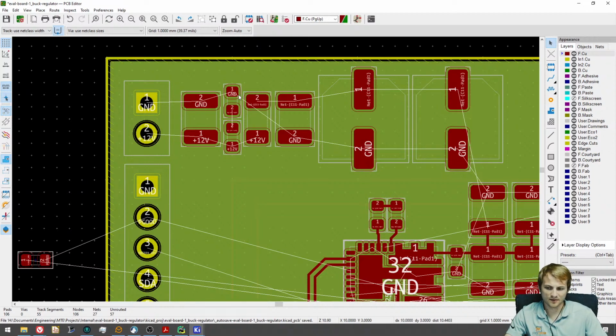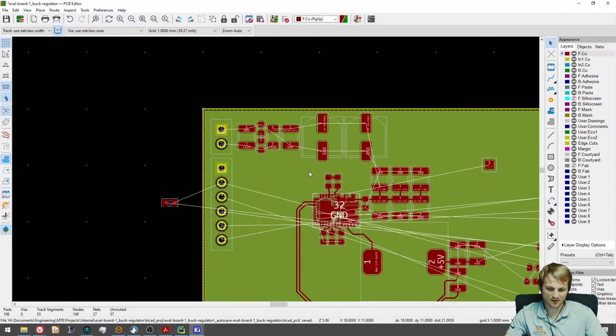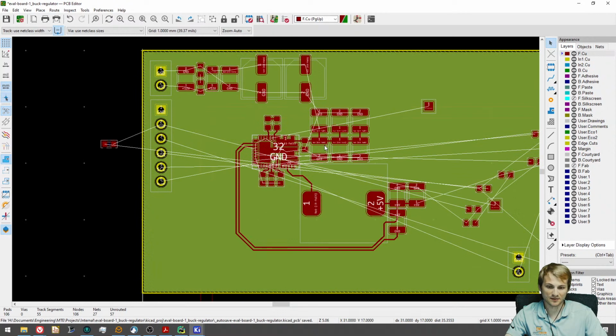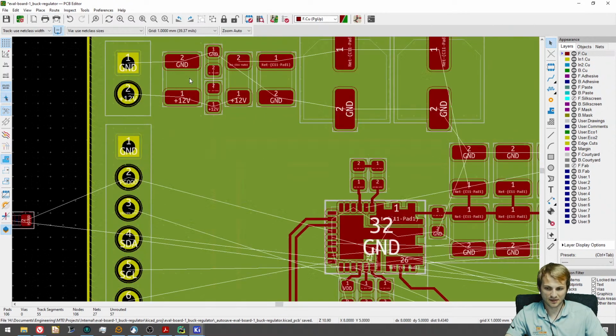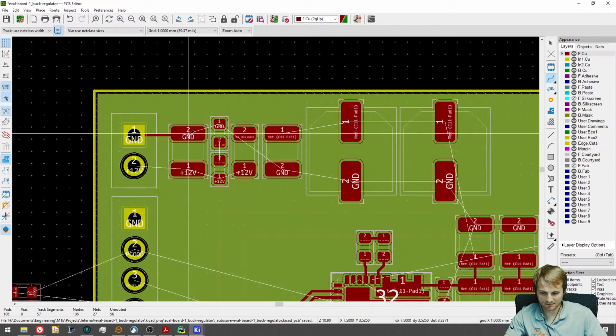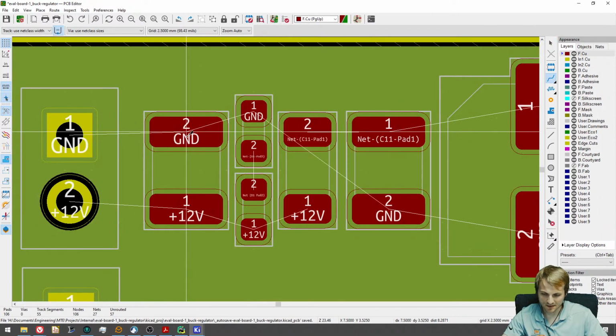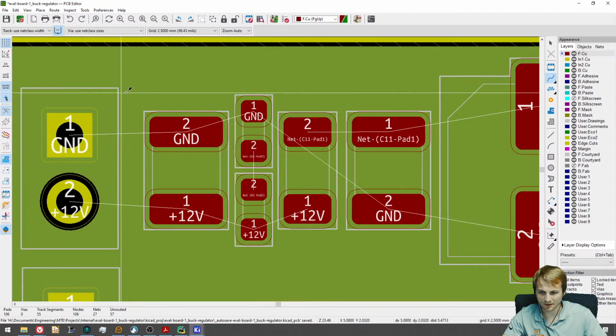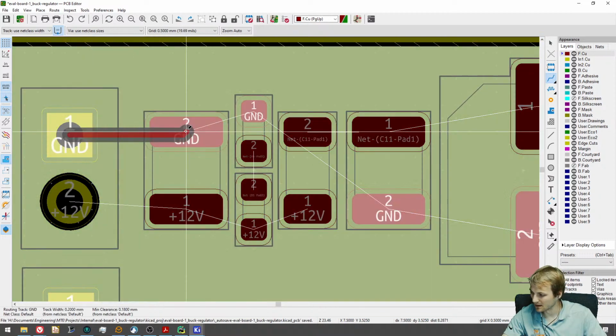It is way harder to do a good 2-layer board than it is a good 4-layer board, because as long as you keep your ground returns just nothing on them, you're eliminating literally like 80% of all EMC failures just by doing that. Same with analog and digital grounds. If you just tie them all together and keep the signals far apart, you're usually better off than most people who get all intricate with it.